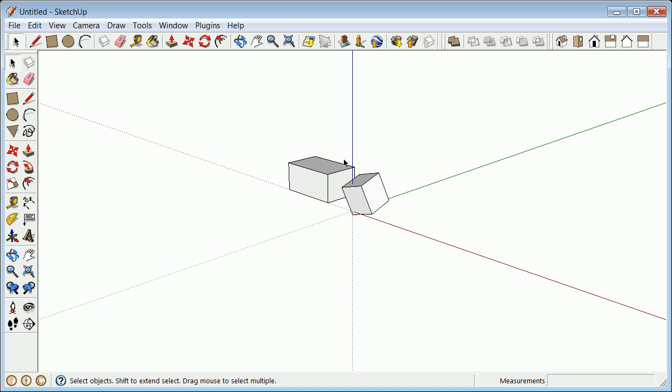So what I'm pointing out here is mostly designed for people who've brought in an AutoCAD drawing and have things that are hanging together as blocks. So we're assuming that you're doing things off of either Design Center in AutoCAD or off of the 3D Warehouse here in Sketchup. And so if you're going to make copies, here's how you do it. You grab your objects. You can build a selection set by holding the shift key. Same standard Windows ways, you know how. You grab the tool you want to do. In this case, we're going to do the move tool.